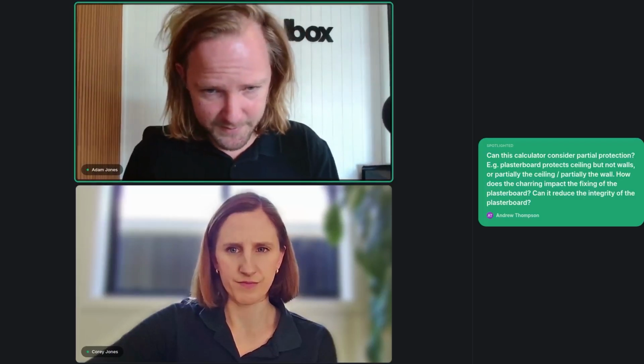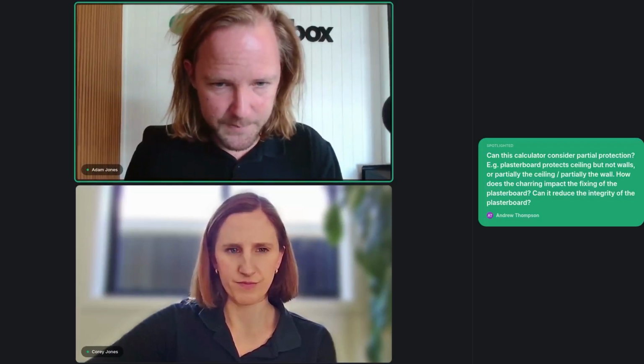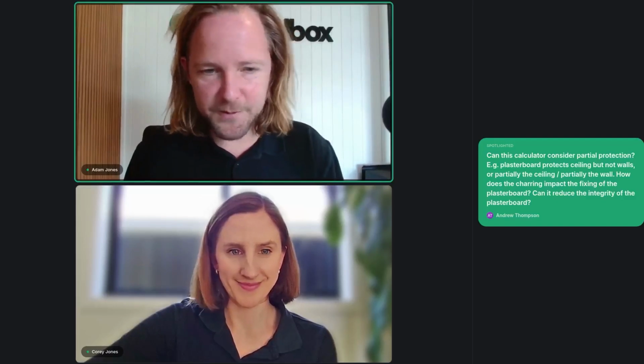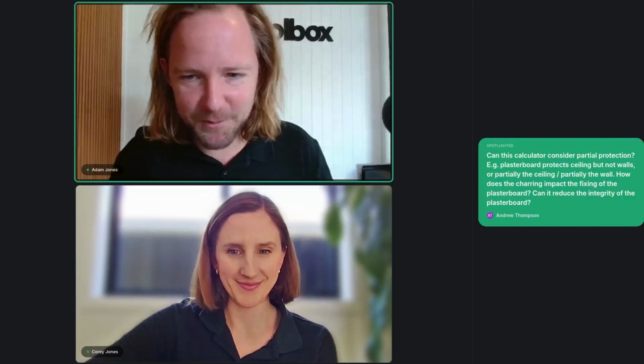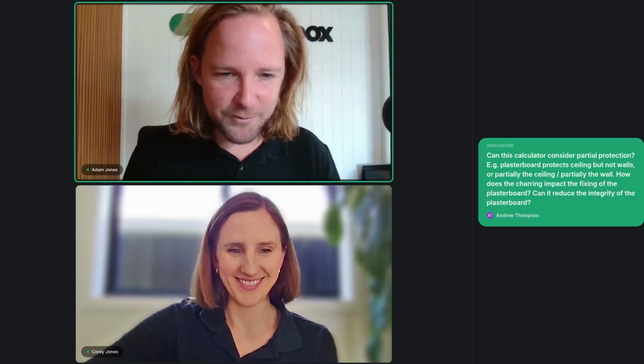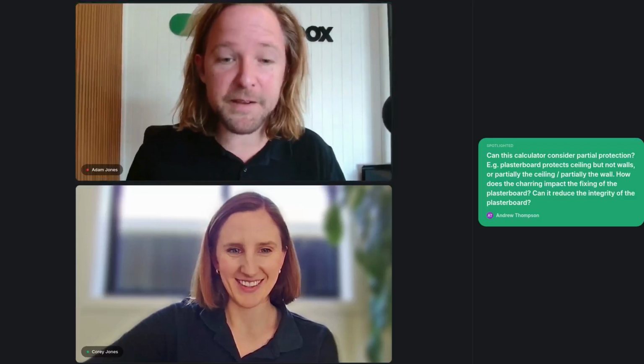But I'm sure, Andrew, I didn't quite get how the charring impacts it. Maybe, Andrew, if you like, feel free to hit me up on LinkedIn or something, and I might try and answer it correctly if I didn't. How does the fixing of the plasterboard work? Yeah, I reckon it comes down to the fire tests and the fire tested systems of fixing. I think the Wood Solutions design guide does cover the fixings a little bit. So there are different guides out there which look at the fixings in general to make sure it's covered.